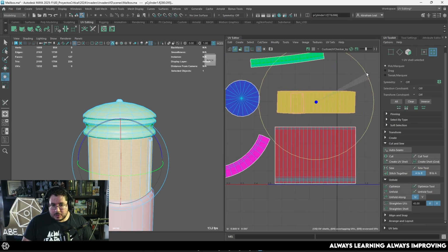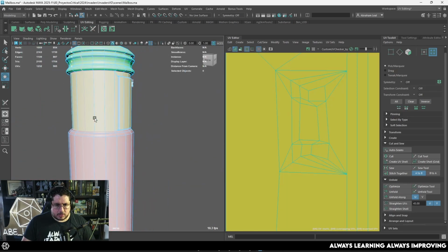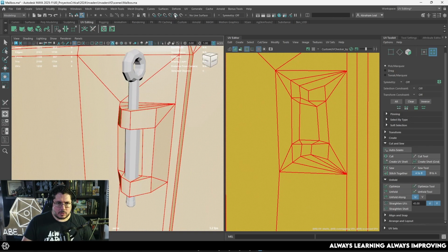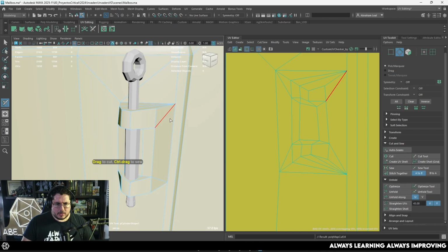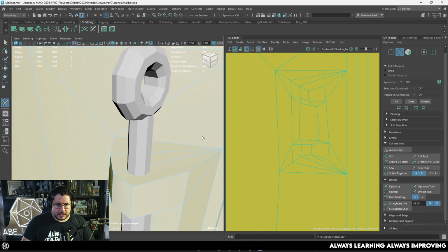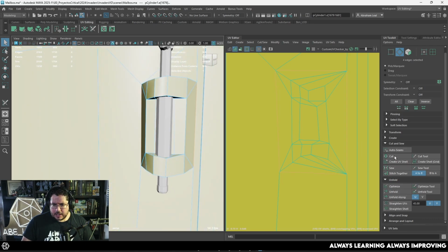This one, I'm a little bit concerned, because as you can see, this is where we have the little element right there, the little hinge right there. It might not be a good idea, actually, to go here into the hinge and remove that hinge from the UV. So that one, if it's not letting you, you might need to do this manually. So I'm going to just select the 4 edges that make up that hinge and then say cut.